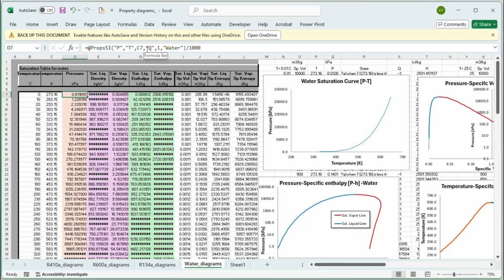this formula. And as we had described in the class several times, when you have a temperature input and a quality input, it doesn't matter for the pressure output whether the quality is 0, 1, or any value between 0 and 1. In any of those situations, it is going to give you the saturation pressure, which is the same for any quality on the saturation curve.